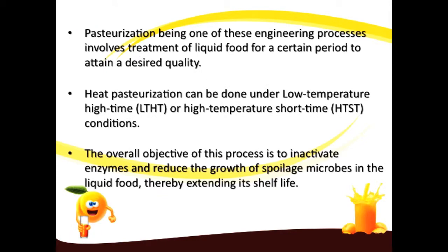What is pasteurization exactly? Well, it is an engineering process that involves treatment, albeit by heat or another means, of liquid foods for a certain period to attain a desired quality. The overall objective of the process is to inactivate enzymes and reduce the growth of spoilage microorganisms in liquid foods, thereby extending product shelf life.